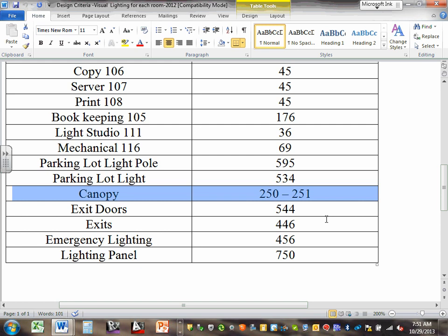Now, the way they go for these lighting fixtures, guys, I know a lot of you have probably never specified lights for a commercial industrial building. The best thing to do is to go to the catalog number example. Can you guys see right here? It says example. If you know the type of fixture but not what catalog number you need, you go to the example. For example, it says LGH 100 M6RW T73120. Can you guys see that? I'm reading right in here.